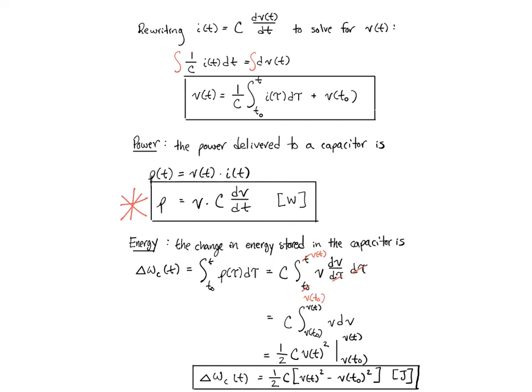So knowing that P equals V times I, we can take the simpler of the expressions, which is I equals C dV dt, and sub that into here, and we see that P equals V times C times the first derivative of V with respect to time. It's a differential relationship there. So it's got V and dV in the expression together.